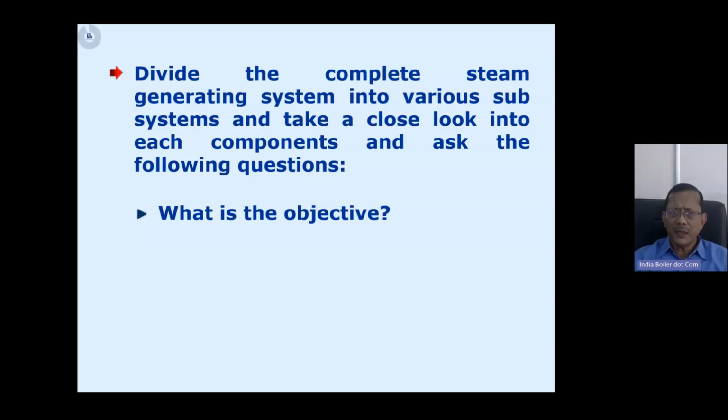But a mechanical deaerator has to remove the dissolved oxygen to the extent of 7 ppb, right? Now that is the extent of its work and it has to fulfill that work. If it doesn't, then the next one, which is taking care of the residual oxygen, that is hydrogen, won't be able to do the job.